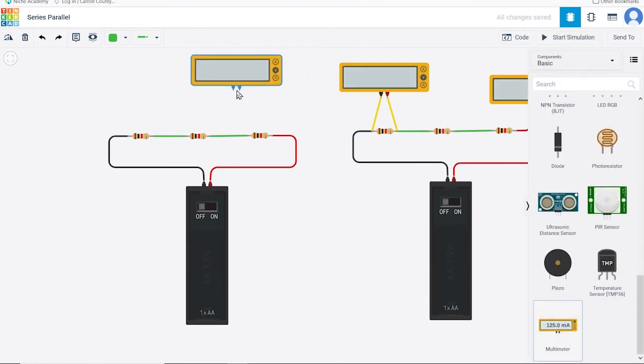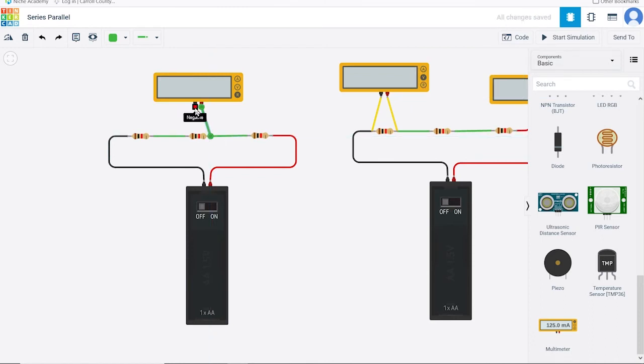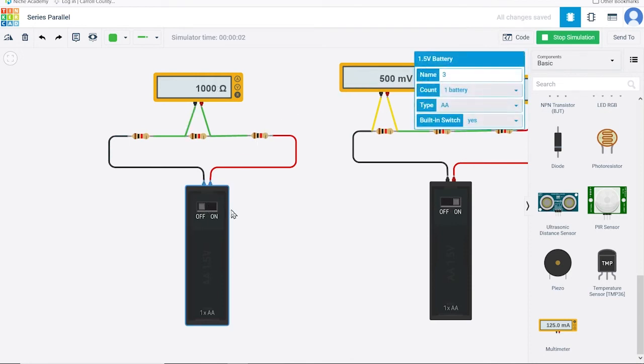Let's connect a multimeter to the circuit on the left and measure the resistance of one of the resistors. Just as in measuring voltage, the multimeter is connected in parallel with the component we want to measure. Unlike voltage, where the measurement is taken with the circuit powered, to get accurate resistance values, the circuit must be powered off. For resistors in series, the total resistance of the circuit is the sum of all resistors.